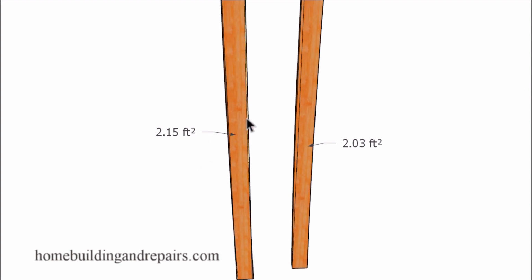This is a 92¼ inch tall wall framing stud with a 1/2 inch bow in it. So we're going to need to remove a 1/2 inch from the center if we leave it where it's at, and 1/4 inch if we move it over.